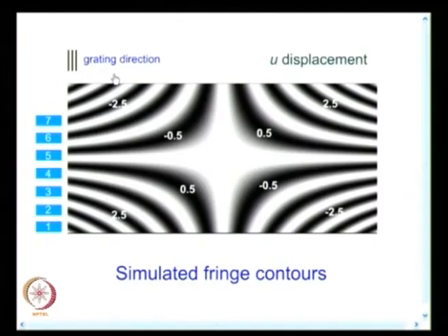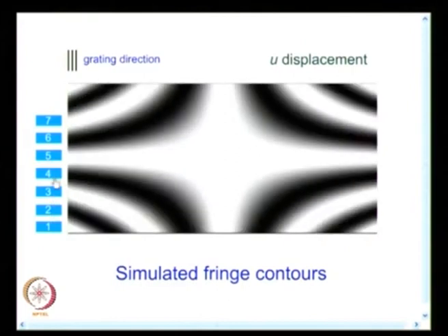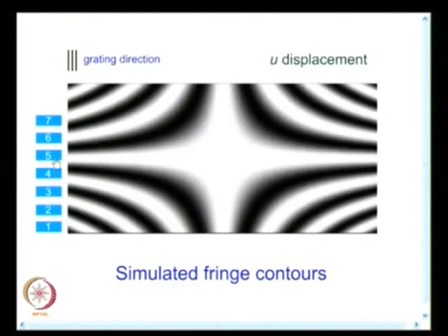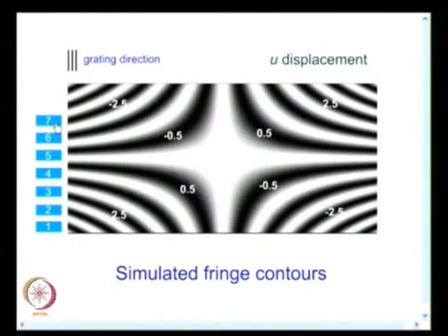And there is a lot of indirect learning. One is, suppose I change the load, and you see this is how the fringes develop. As the load is increased, more and more fringes develop, and this is a very key piece of information in most experimental techniques, as an auxiliary method to label the fringe orders. Another thing you find is that the fringe thickness is different.